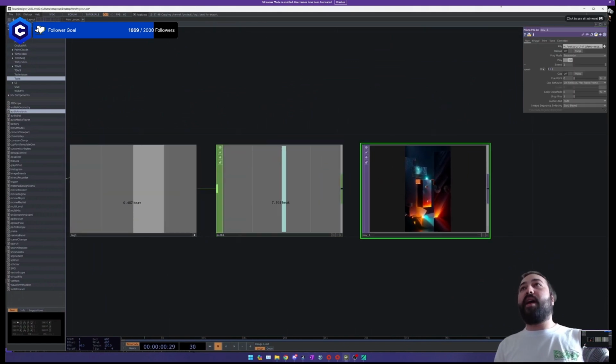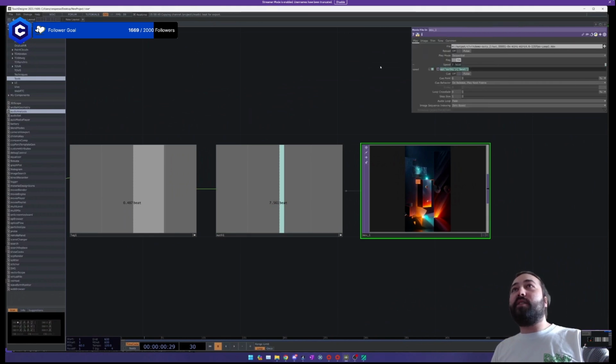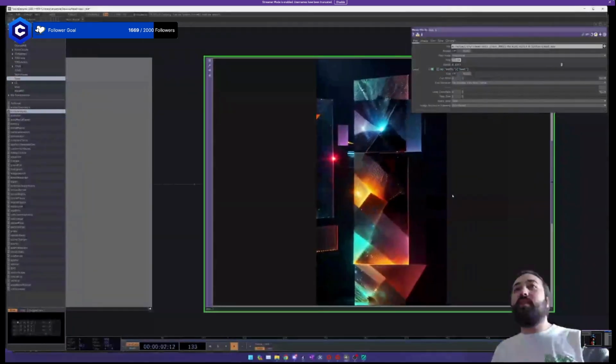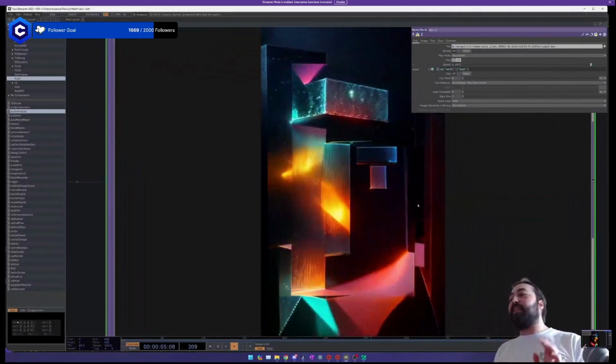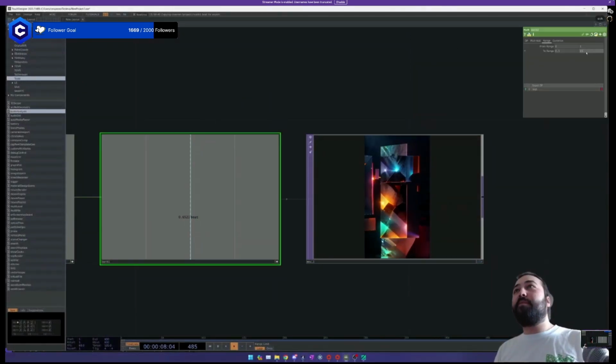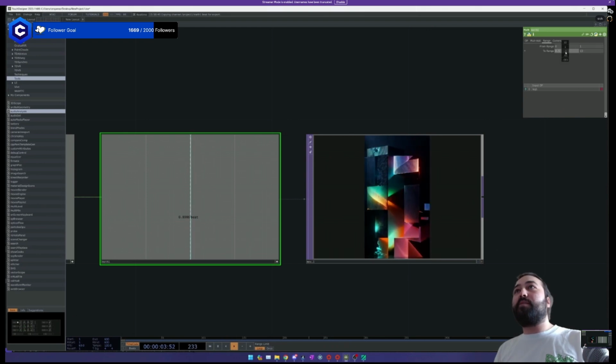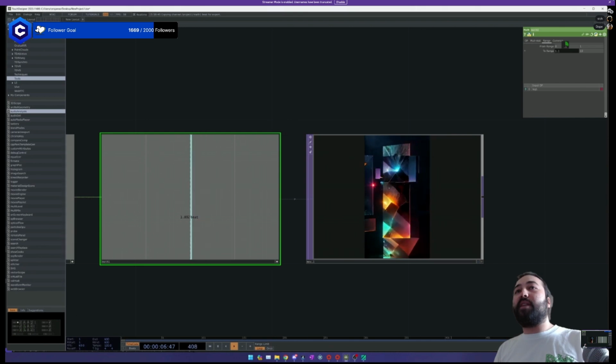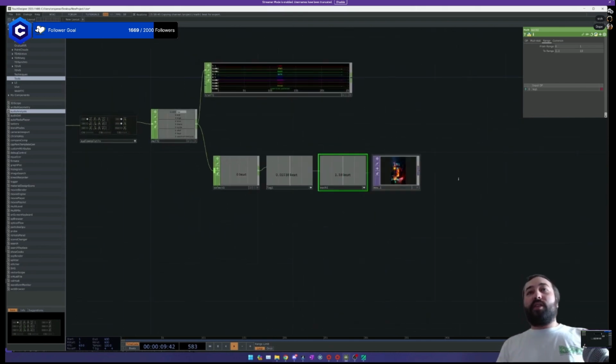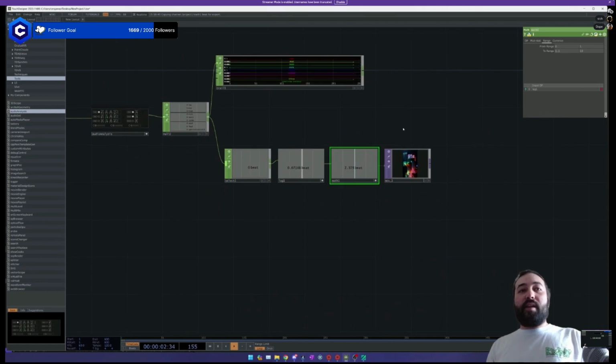So now we're going to map that to this value. So if you click the little viewer thing in the bottom right corner here, and then click on this and drag it over to the speed, and then do chop reference, it's going to automatically make this little Python reference essentially to this channel. And now it's just connected. So that is the essence of the audio reactive setup. I'm going to make it even faster, actually. Yeah, that's pretty good. And maybe have the ambient speed be a little bit faster. So that's kind of the basis of the audio reactive setup.